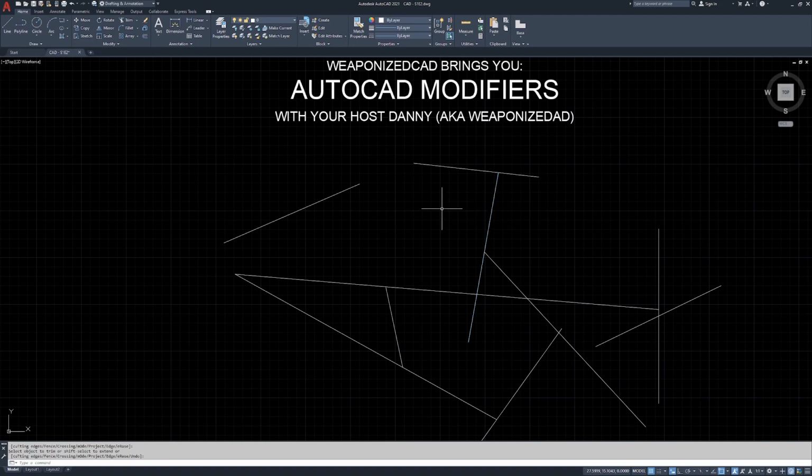Quick trim and quick extend are good when you're trying to move quickly, but it doesn't give you as much control as using standard trim and standard extend. Because we changed the mode in the trim command down here, it's now set to standard. I'm going to hit escape a couple times. I'm going to go up to the extend command, and I'm going to hit the mode.